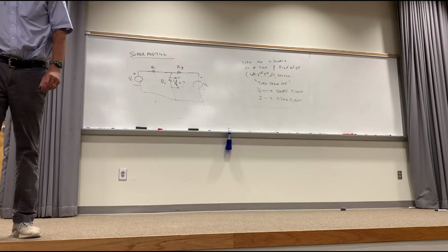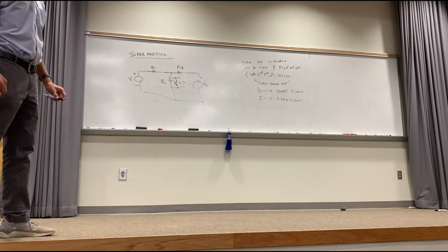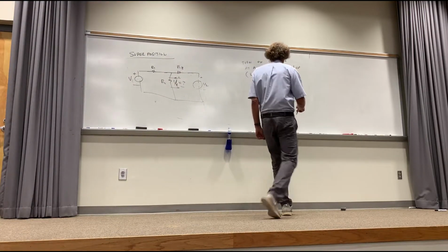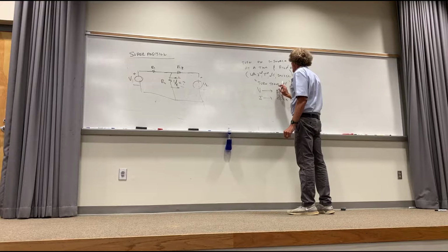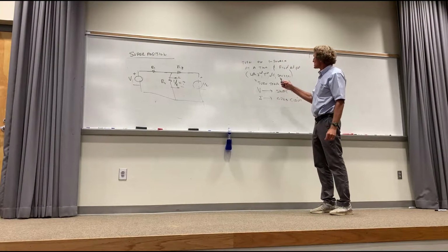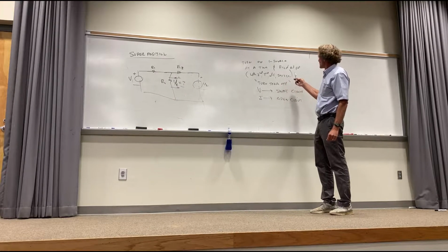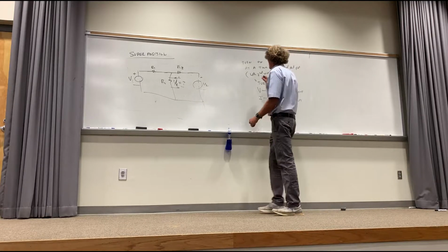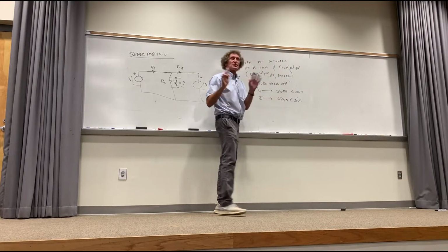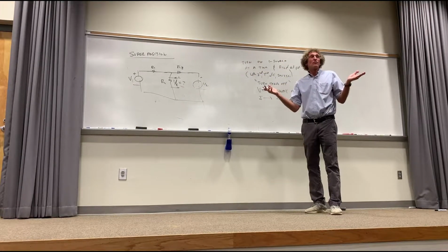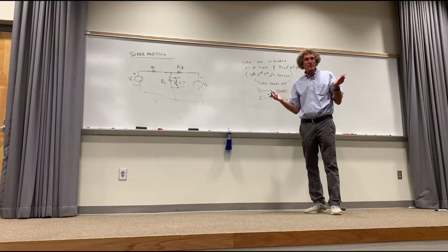Yes? He's asking about the second, third sources. Oh yeah, you turn off the sources. Second, third, etc. sources turned off. Turn them off. Let me give you an example. When I say turn them off, voltage sources become short circuits, current sources become open circuits. Got it? If I do an example, this should bring it to life, I hope.